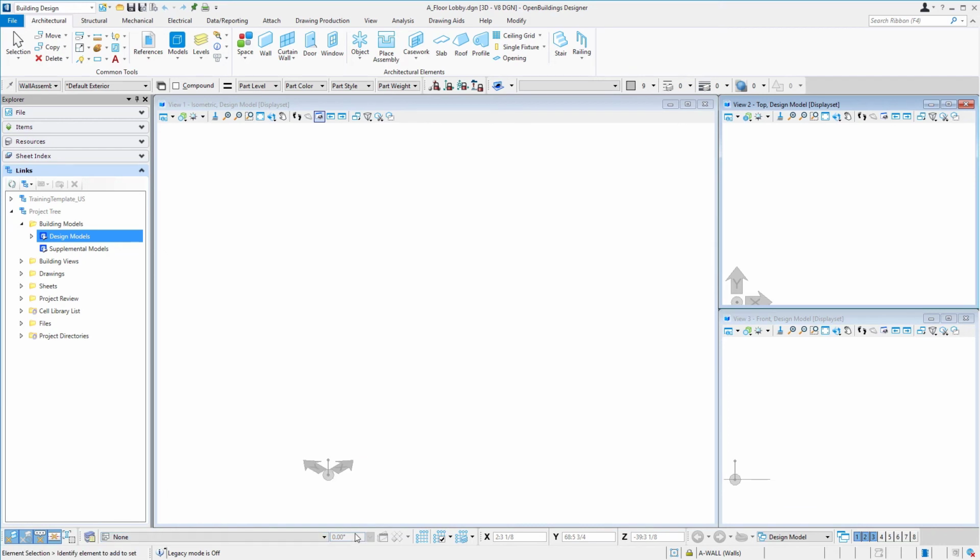There are some additional tools at the bottom of the interface, and we'll cover these in the next session. We have a floor manager and grid manager, and we're going to use those floors and grids to help keep our various models aligned in 3D space. We have the AccuDraw key-ins, and we'll talk about AccuDraw once we start placing elements. And then note here, we've got these 3 views open. This is how we'll view the model. You can see down here, you can have up to 8 views. This is what turns them on and off. So we have 3 open, or toggled on, right now. Those views can be set to different orientations. For instance, we have an isometric view here, a top view, and a front view. We can put different display styles on them and so forth. And you can move from view to view as you're working. So we'll go through that as we start modeling.